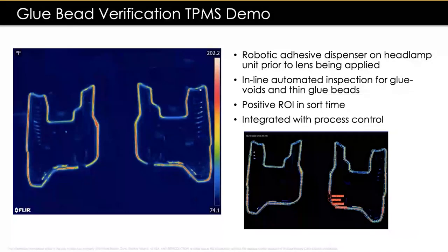The issue with that is, how does a system really determine what thin glue is and what thin glue isn't as far as a pass or fail? What would end up happening was the channel in which the adhesive was applied, imagine a U-shaped channel. The parts, these plastic parts coming out of the injection molding process, had warp into these bridges and warpage on the walls.